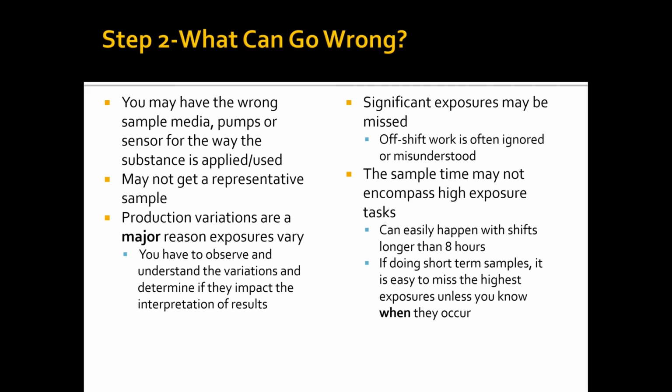Oftentimes, significant exposures can be missed if they're done off shift work. I do a lot of work in foundries, and refractory work, removal from furnaces and ladles, is often done on off shifts on weekends. And oftentimes your contact, if you're not that contact, doesn't even know that work is going on, and yet those are extremely high exposure tests. So asking questions about things based on your knowledge of the process can be very important.